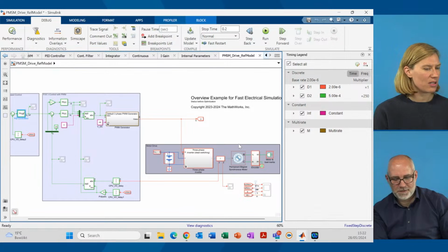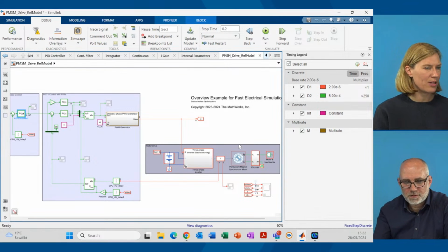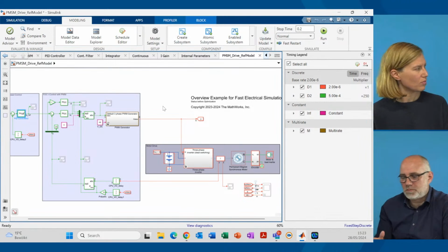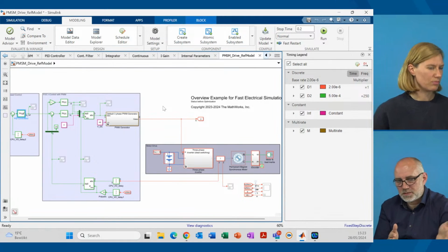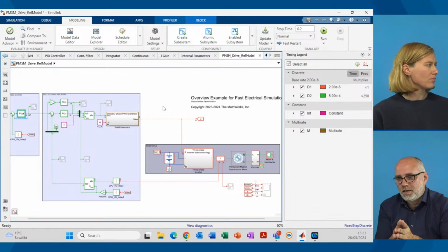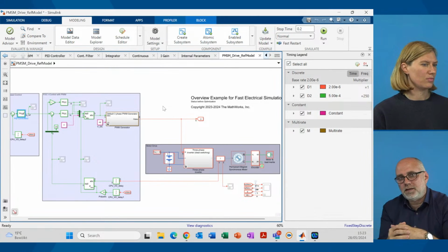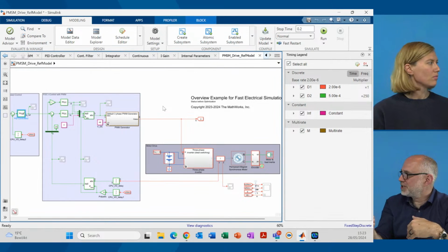Yeah. So maybe as we're still working with sort of desktop simulation, let's go back to set the global solver to be variable step and also remove the local solver from the Simscape model. I think the main idea here for the variable step is that the controller is still in fixed step, time discrete, but the PWM has this high accuracy of 2 microseconds compared to the 500 microseconds of the updating cycle of the duty cycle. So most times nothing changes.